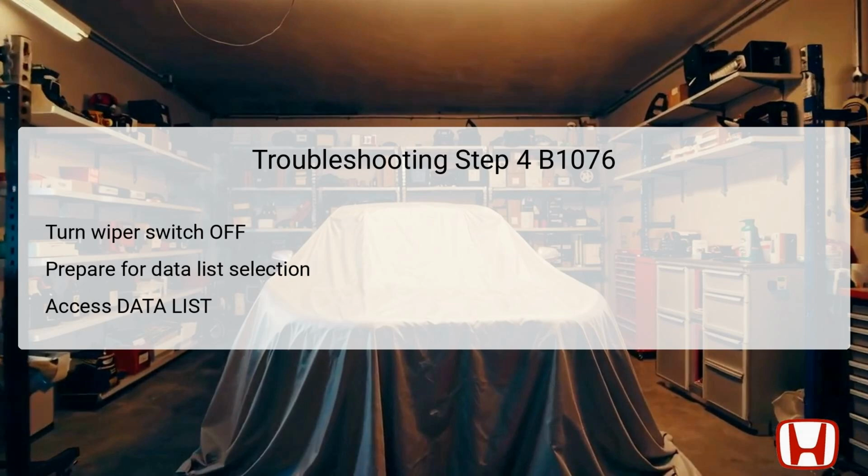From here, select the windshield wipers option from the Body Electrical System Select menu on the HDS. This menu allows you to access the data list, which is a vital component in observing real-time data related to various electrical systems. You'll want to focus specifically on checking the on-off information of the windshield wiper switch backup in the data list. Observing this data helps in confirming whether signals from the switch are being transmitted correctly or if there are underlying issues needing attention.